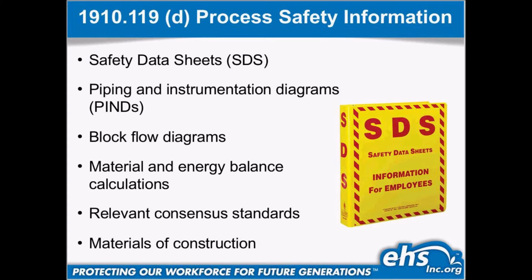So we had to empty it, take it apart, and look inside the machine. What we saw was really interesting: the titanium bolts were being destroyed by the chemical itself, because there was a little too much iron in the concentration of the hydrochloric acid, and that was affecting the titanium and also the type of seals we had. So we had to switch everything. We had to put Viton in it.